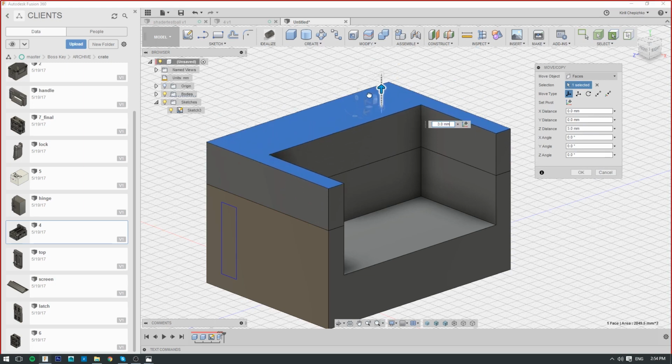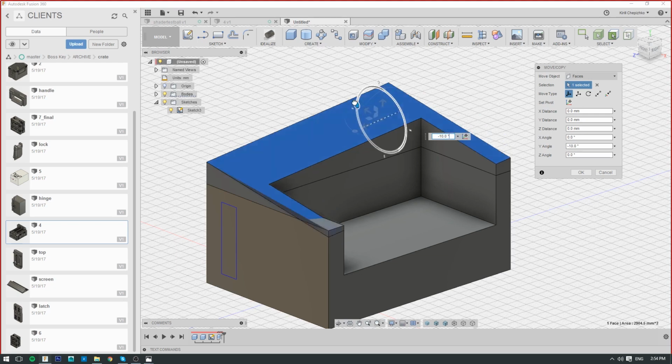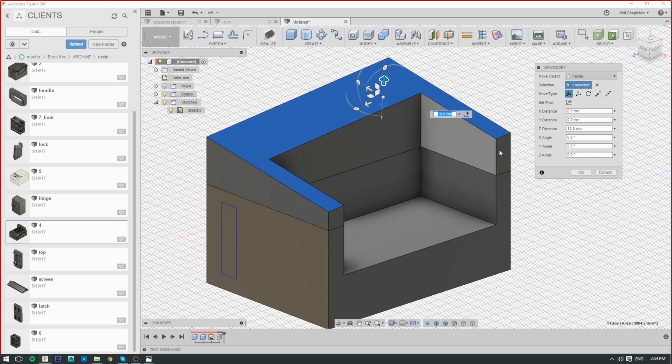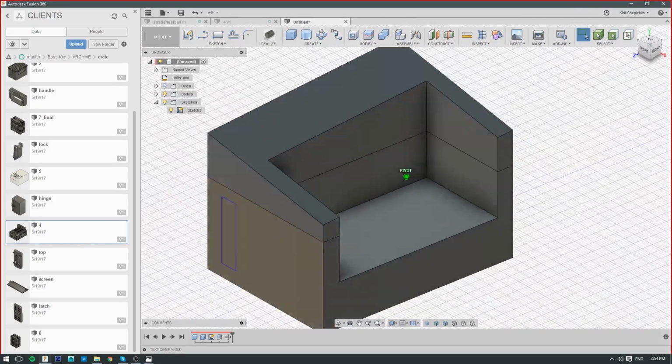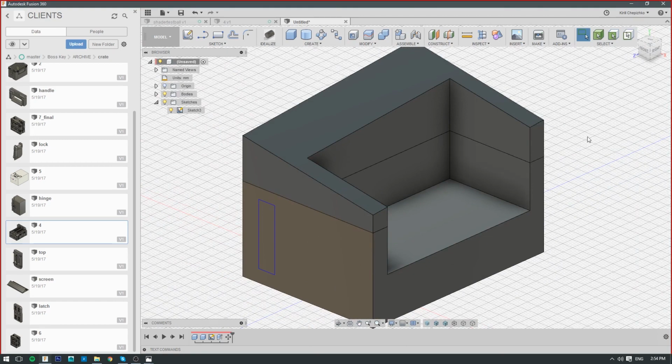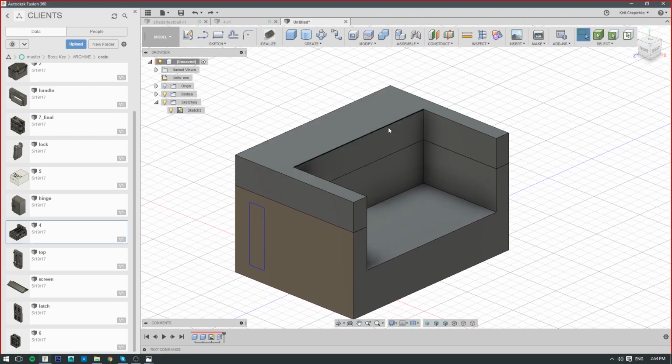You technically can move the face. You can actually rotate it and stuff like that. It may break your design, but it's possible. They opened this option for us, but in return, what we got is the default action was moving a body, which was very convenient, and moving a face is not.